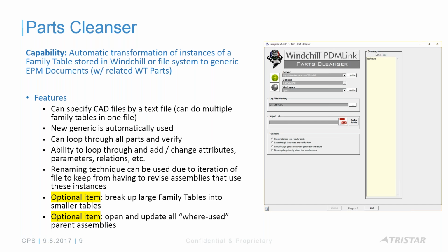So the Library Wizard, let's say for example you're doing things like piping and you're building piping mock-ups inside of Creo, and you've got elbows and fittings, etc. What the Library Wizard can do is analyze an assembly, and it can take some of the fittings or any number of the fittings that you have, elbows, bends, faucets, etc., and valves, and it will automatically push those to the library inside of PLM. The quoting, the catalog composer, and the component instructor modules, those are kind of part of the overall sales configurator. We're going to get into that.